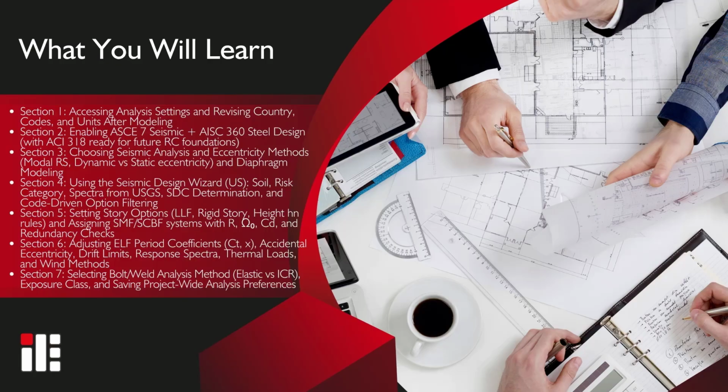In this lesson, we'll configure analysis settings in ideCAD: country and codes, ASCE 7 seismic with AISC 360 steel, and diaphragm and eccentricity options. You'll learn how to use the Seismic Wizard to pull USGS spectra, set SMF and SCBF with R, omega, and Cd, and fine-tune drift, period, and redundancy factors.